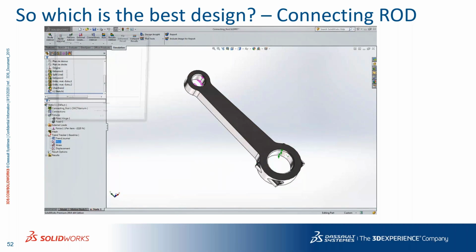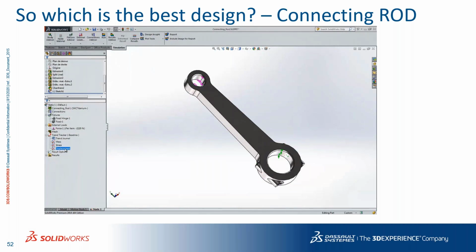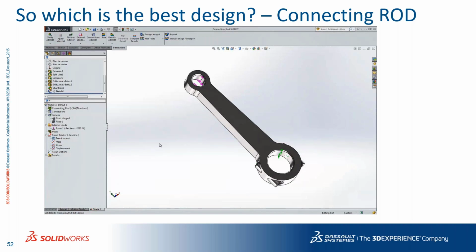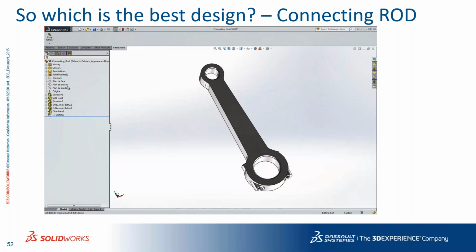So this is my reference. I'm going to vary it and check how the mass is going to vary also. You can see that these are the plots which I'm going to obtain from the trend tracker itself, which is the mass, stress, and displacements. It will also add sensors here, what you're observing: mass, stress, and displacement sensors.